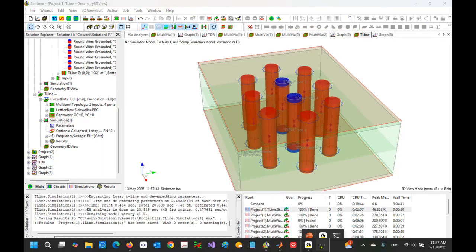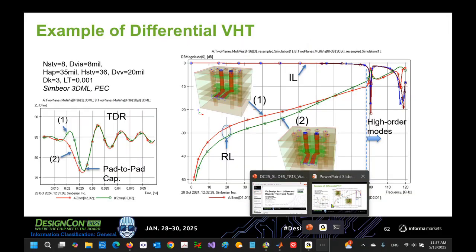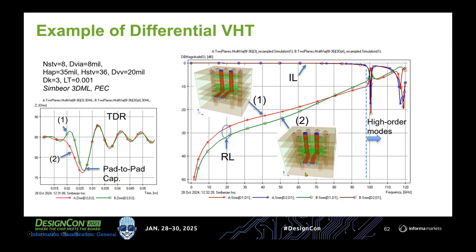And for the differential case, the transition is also, you will have the same brick wall at a little bit lower frequency because of the transition into this. T11 is pretty much the same in differential, but because the whole pattern is wider, it takes place at slightly lower frequency. So this brick wall is unavoidable. You cannot overcome it without reducing the size of this transition.